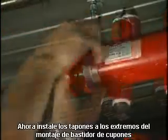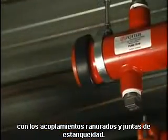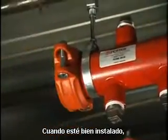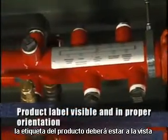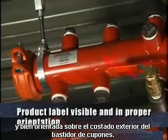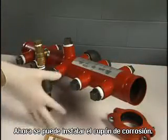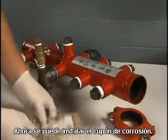Now install the end caps on the ends of the coupon rack assembly with the grooved couplings and gaskets. When installed properly, the product label should be visible and in proper orientation on the outside edge of the coupon rack. Now you are ready to install the corrosion coupon.